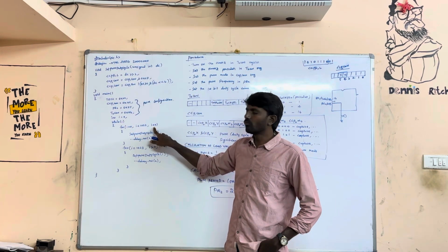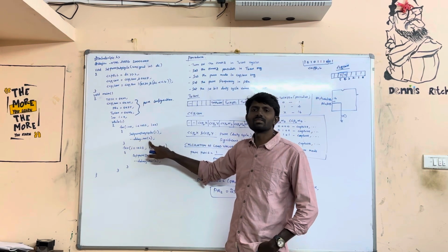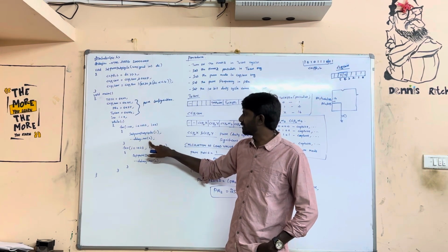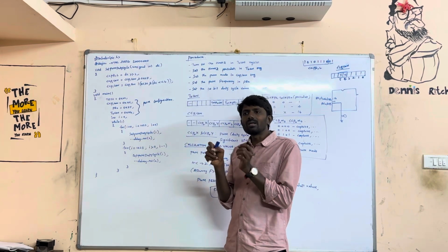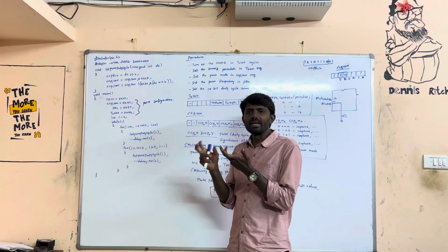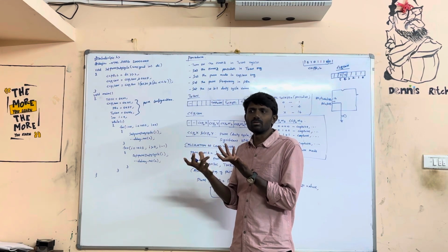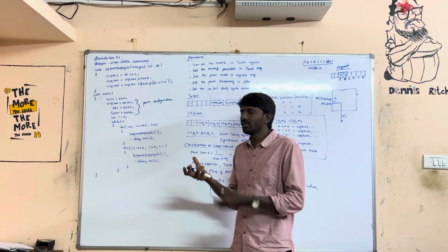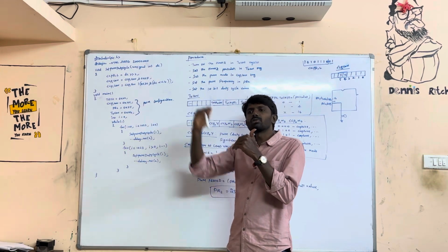Next you are incrementing by 1, changing the value by 1. Every time you are giving some delay, 2 milliseconds. So now the value is 1. Maybe with 1, I don't know how much the voltage difference will be. It may be very little, so you cannot see any difference in the LED. So 2, 3, 4, like that.